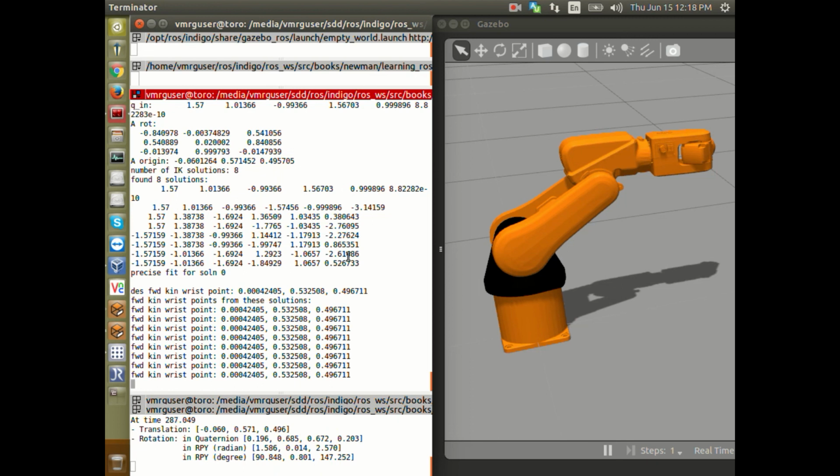Okay. So again, in your homework, you'll do something much simpler, just using KDL or TRAC-IK. They have the same API, basically, and you do this. But now, this is a simpler problem, and we often won't need to use forward kinematics directly. What we will need to do is inverse kinematics, because when we need to grab an object, we need to know the joint angles for that position. Okay, so next week, we'll look at inverse kinematics, and a little bit more on motion planning, and then we'll finally move to actually grabbing the objects. Okay? Thank you very much.